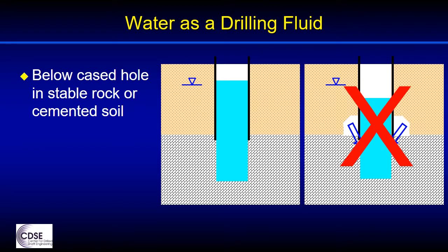The voids could lead to subsurface subsidence around the casing, even extending all the way to the surface in the form of sinkholes. If the casing is temporary casing, we could lose so much concrete flowing out into the void when the casing is extracted that there could be a breach and mixing of concrete with the water that's in this void.